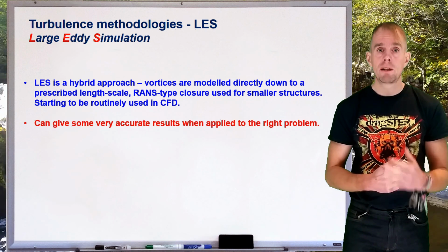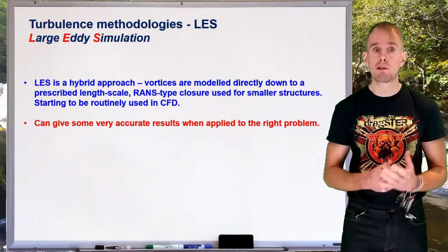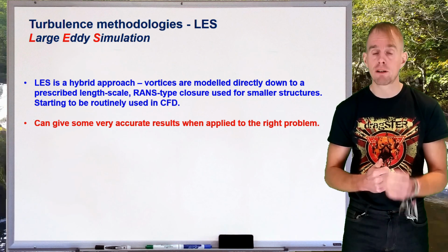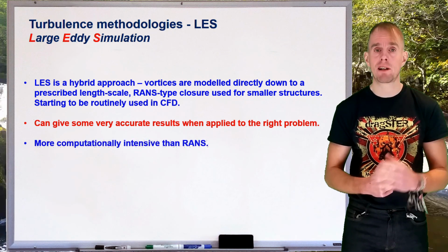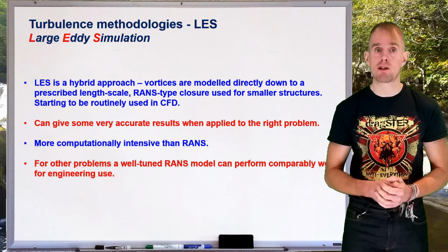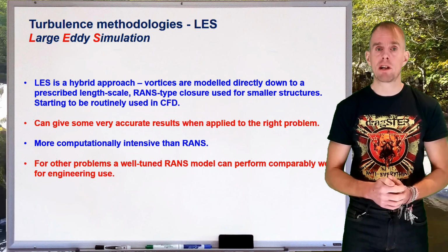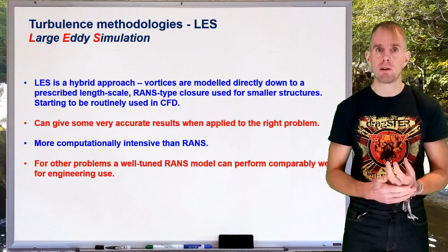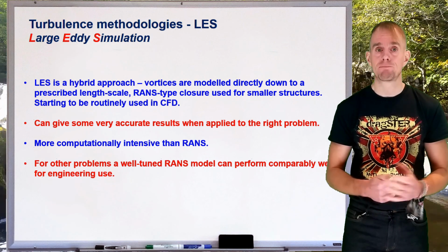Large Eddy Simulation has been used routinely in computational fluid dynamics for some years now, and can give some very, very accurate results when applied to the right problem and when tuned in the correct way. It's more computationally intensive than Reynolds Averaged Navier Stokes alone, but it's interesting to note that for some engineering problems, Reynolds Averaged Navier Stokes, when tuned in the correct manner, can perform comparably well.